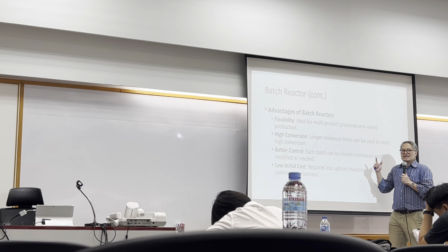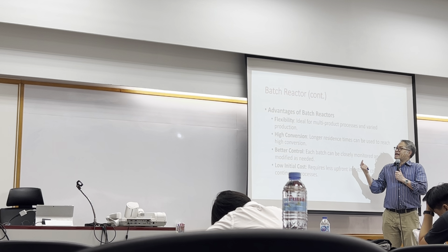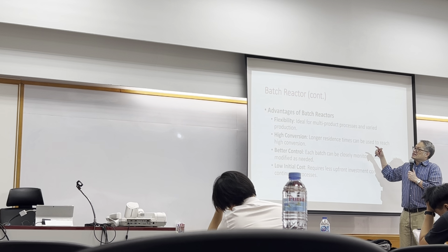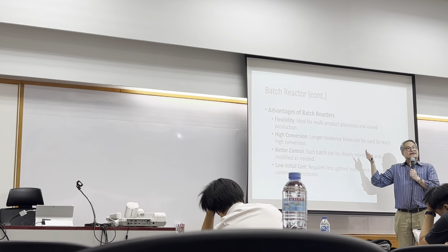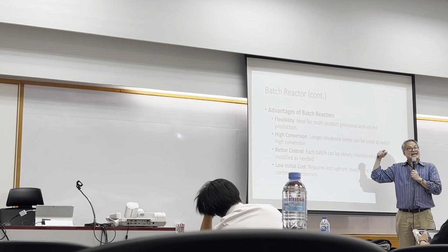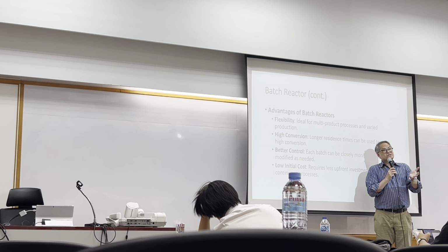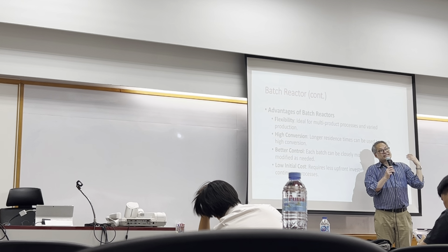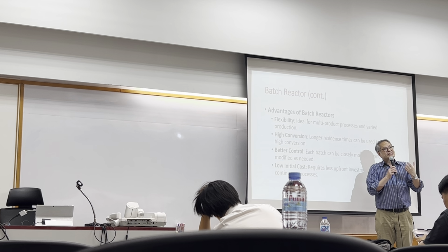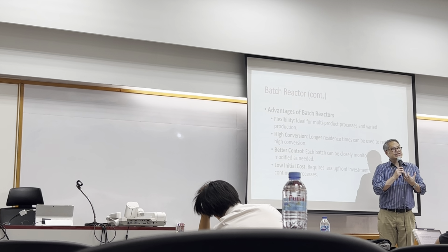Batch reactors are usually used for liquid phase or aqueous phase reactions. Gas phase reactions, not so well; they don't usually use it. But sometimes they use the batch reactor for gas phase reactions when they want to do kinetic data analysis, like we did in chapter 3. We use a batch reactor to get concentration versus time data and use that to develop our rate expression. So that's a rare case where we use it for gas phase reactions.